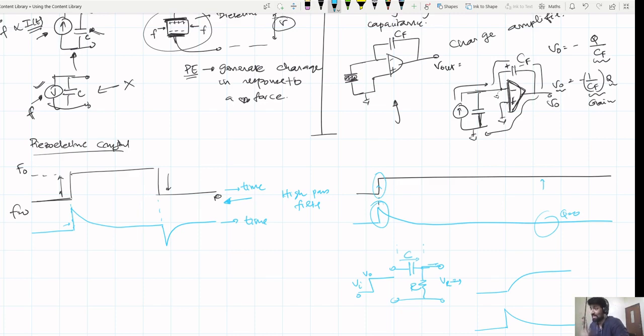Here, see, this is basic signals and systems, and we also discussed this in one of our earlier modules. So I suggest that you go back and brush up your fundamentals on high pass filters, band pass filters, and all these different filters. I'll propose this: if you have MATLAB or Simulink, build a high pass filter and apply a step input and see what the difference is. In fact, build a first order high pass filter. This is the first order high pass filter. You can't have a single order band pass filter. Build a second order band pass filter, that's the lowest order possible, and then look at the responses.